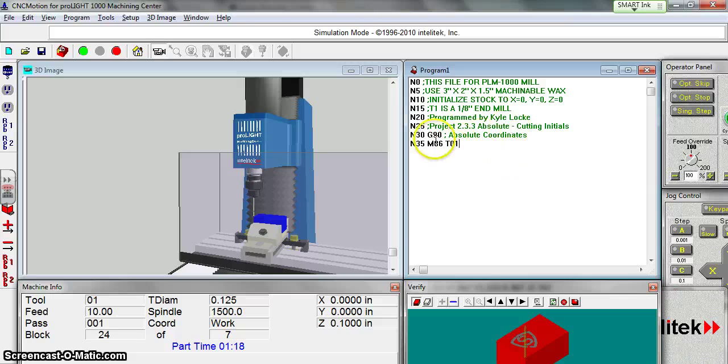and I mentioned to you before that you need to make sure that you do not have spaces between your letters and your numbers. You can have spaces here, or you can take them out if you choose. It's a little harder to read when I don't have spaces between the 6 and the T, but it's not needed. You need to make sure that you can identify different words in your program so that you know that a letter precedes a number, comes before a number, and there's no space between that. Otherwise, there will be an error whenever you run this code.